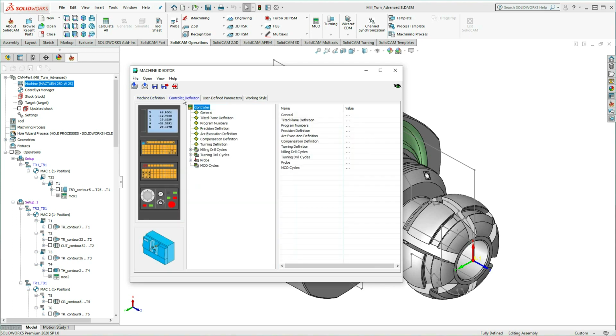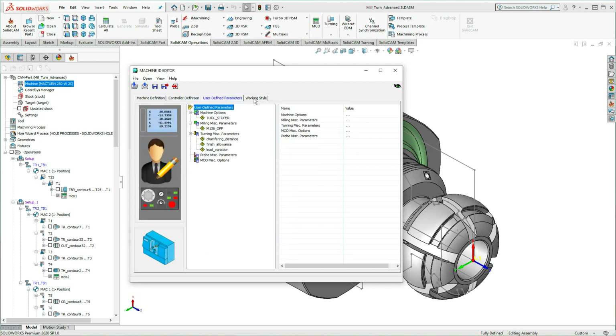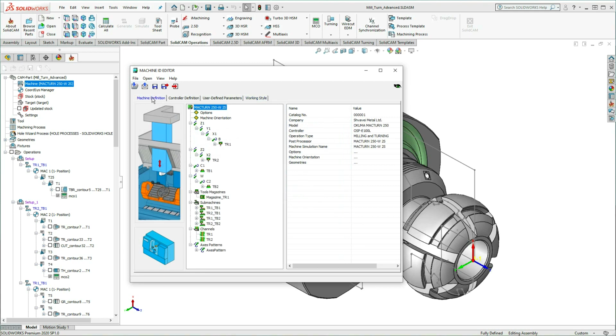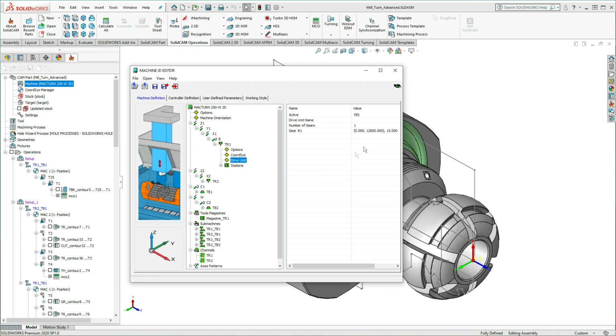The VMID defines everything SolidCAM needs to know about the machine and more. For iMachining specifically, the Defined by VMID feature takes the values from the machine definition. In this case, we have two turrets of different types that have varying parameters. Axes may have different max feeds, for example. In this case, spin max differs, and in some cases, power max can also differ. Efficiency is taken from the station's data, which can differ as well.